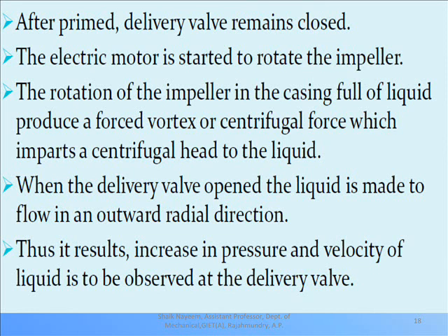With the help of an electric motor, the impeller rotates. Because of this rotation of the impeller, the fluid gains centrifugal force. After reaching the maximum limit, the delivery valve is opened once again. The fluid which has gained centrifugal force then moves in the radially outward direction.